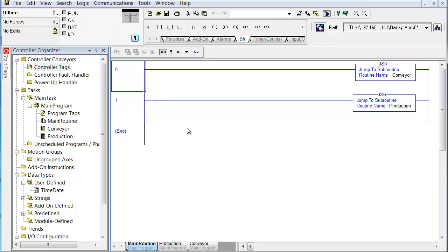These changes could all be made online very carefully. You can do almost anything online that you could do offline, but if you make a mistake you can't correct it online. So once done, you cannot edit it online. Once the Logix Engine places the instance somewhere in memory, it's not allowed for you to go and edit that instance. You can delete the instance and reinstantiate it the way you want it or where you want it, but you can't edit it once it's created online. You have to go offline to edit it, or if you're online you have to delete it and redo it. We're offline.